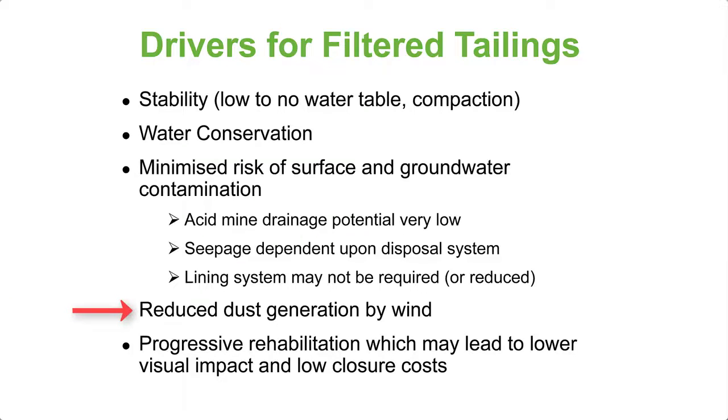It may also be possible to reduce dust generation by wind from your facility, and it may also be possible to do progressive rehabilitation on a much earlier basis and not leave it right to the end of the mine life. So it lowers the closure costs. So these are really good drivers for filtered tailings.